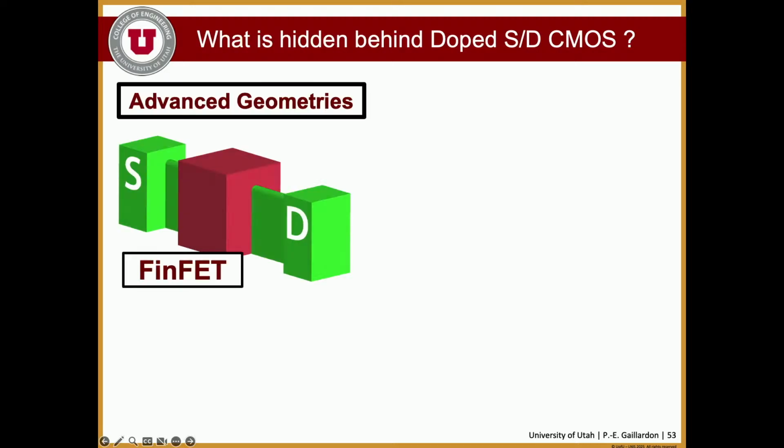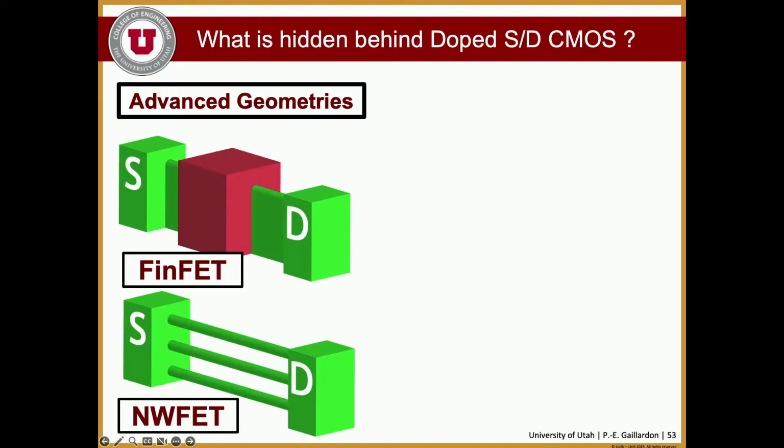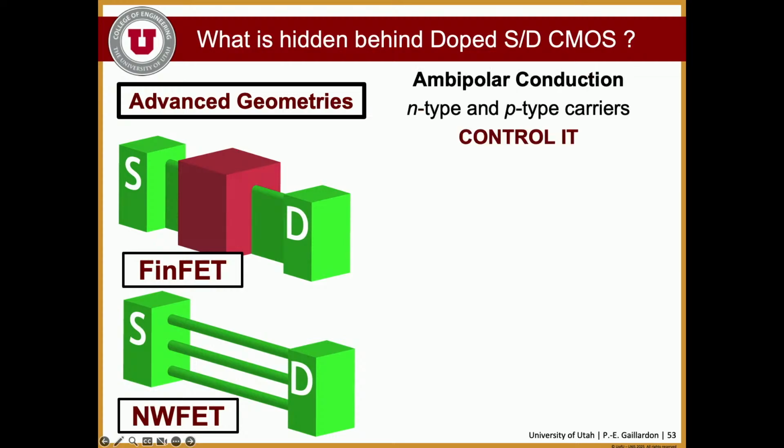I don't think we really went into device topology and device physics just yet in this boot camp. I'm going to try to venture there. But modern transistors are based on semiconductor, so silicon or silicon germanium or whatever, and you have the gate control around that. It's electrostatic doping, and we're using FinFET topologies. It's moving to CFETs and a bunch of different structures, such as nanowires, so you have even better control.